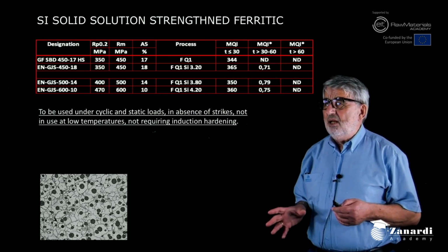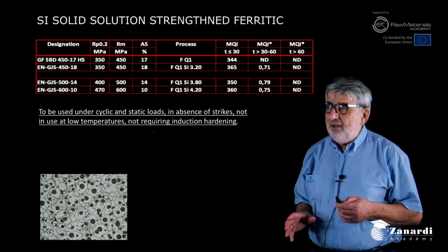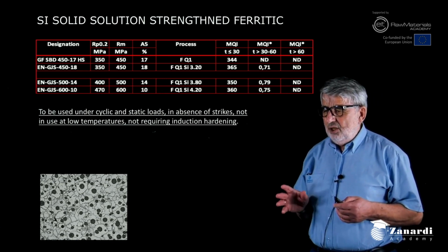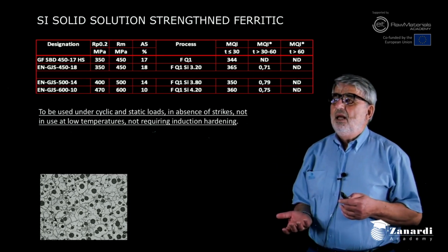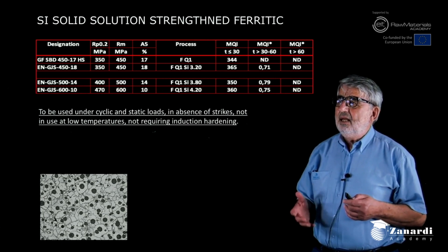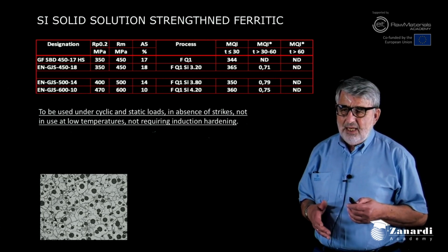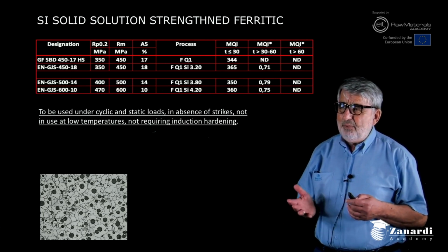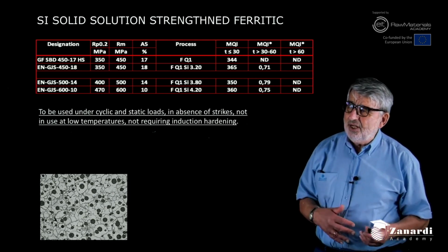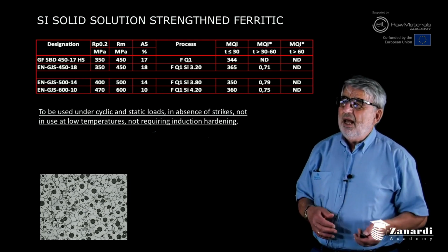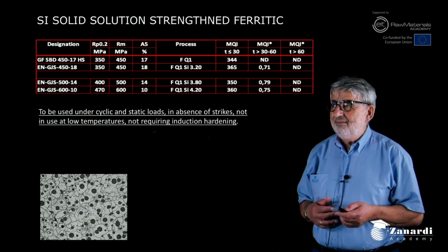This material was well accepted even in the automotive industry because it avoided the need to use ferritic-pearlitic grades, with better machinability associated to the uniform and constant hardness.